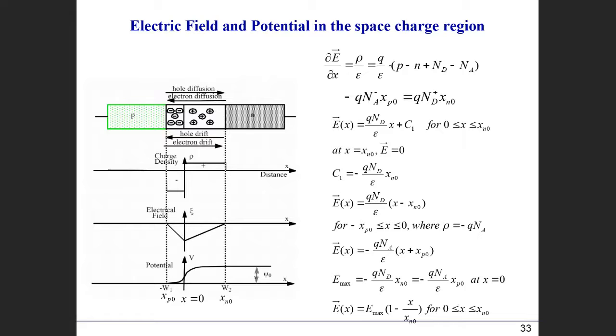Okay, so in this slide, I think in 339 you already did this PN junction diode, but you can treat this one as the review for the 339. So I'm going to follow this step and then try to calculate the electric field and potential, especially in the space charge region. In this specific example, we're going to look at the PN diode. As you can see, PN in here. The P side we dope with Na, and then the N side we dope with Nd, right?